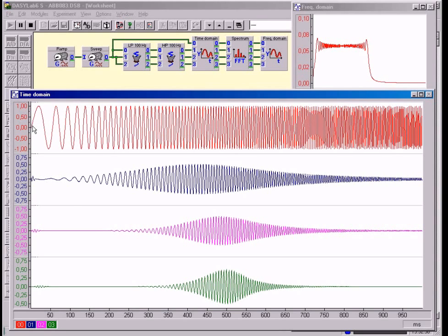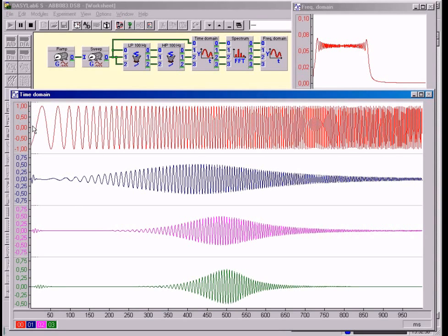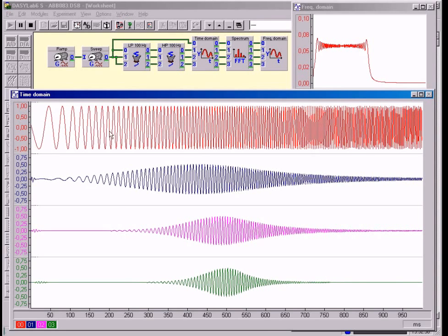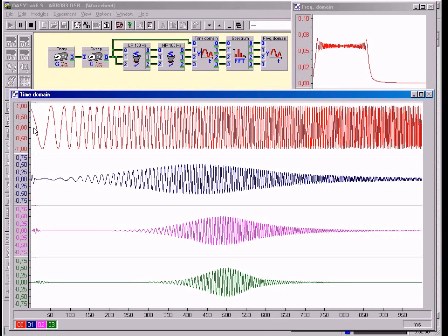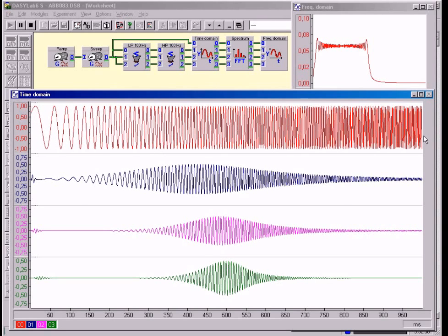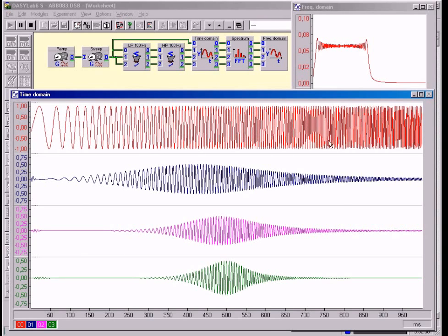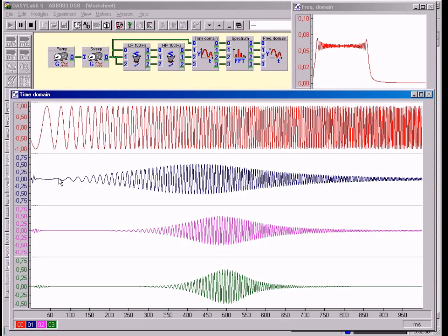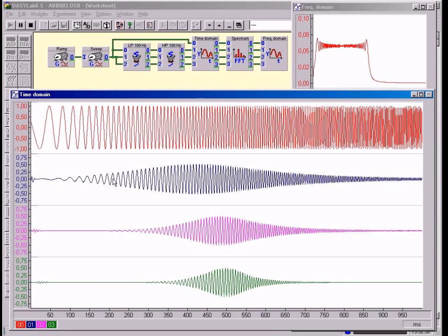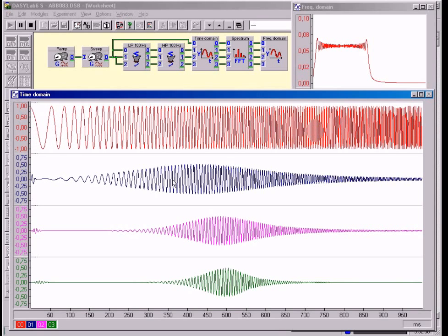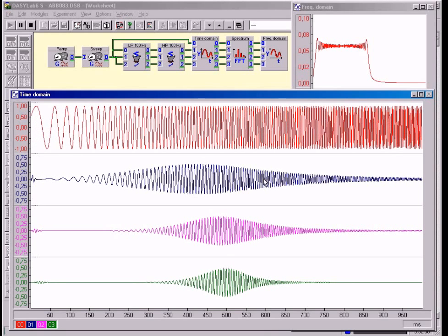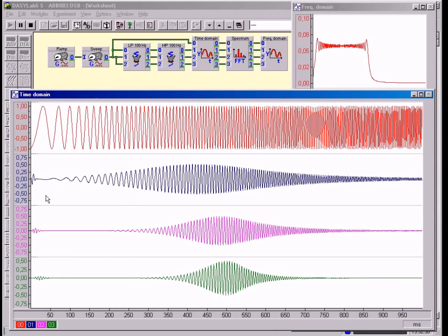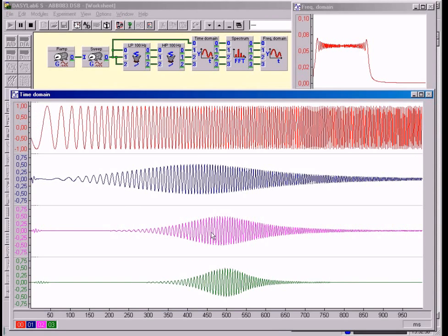In this illustration, the whole sweep signal is represented on the screen. On the left, the starting frequency, and on the right, the stop frequency. In this way, the curve of the output signal on the screen does not only show the time curve, but also indirectly the frequency response of the system under examination. The time axis is indirectly the frequency axis too.